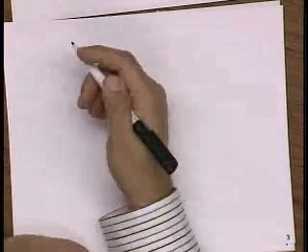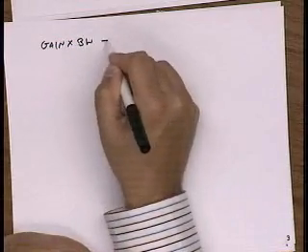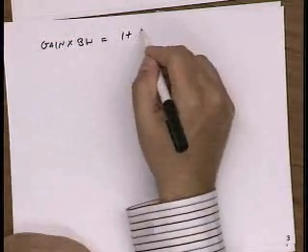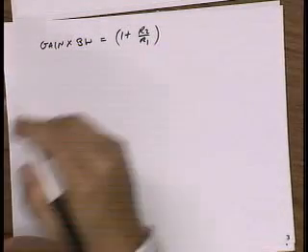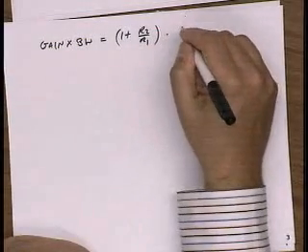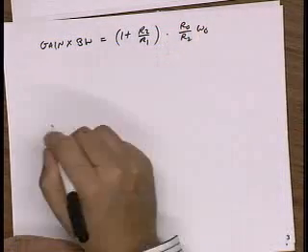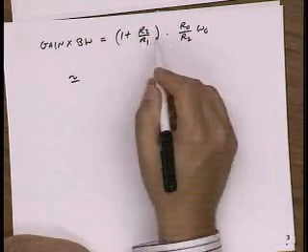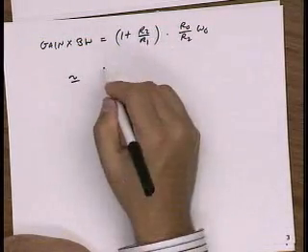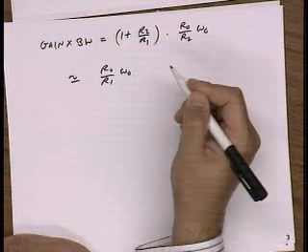Okay, so then the next question is, well, how good is this? What kind of gain bandwidth product can we get out? So let's multiply the closed loop gain times the bandwidth. The closed loop gain, the peak value, is 1 plus R2 over R1, and the bandwidth we found to be R0, R2 over omega naught. And if I assume that this is much bigger than 1, the R2's cancel out and I get R0 over R1 omega naught.